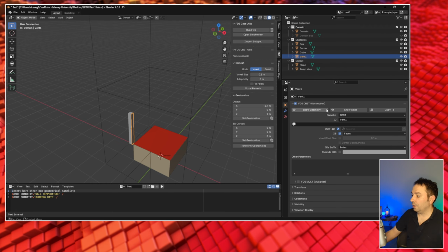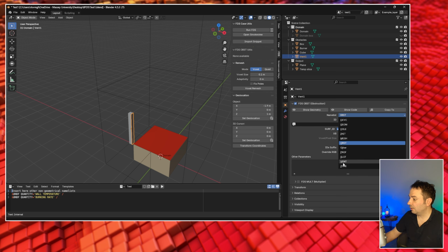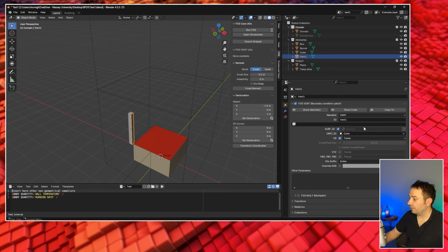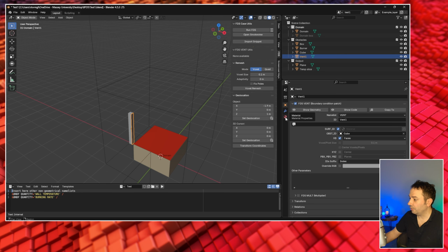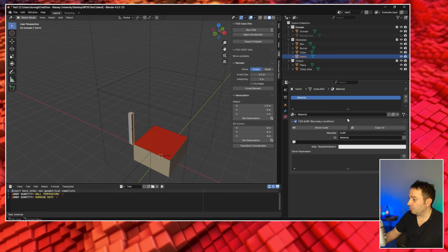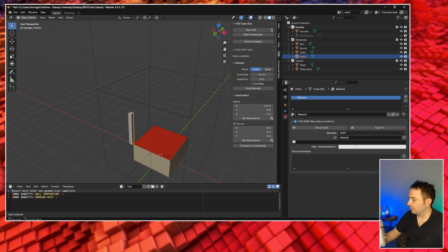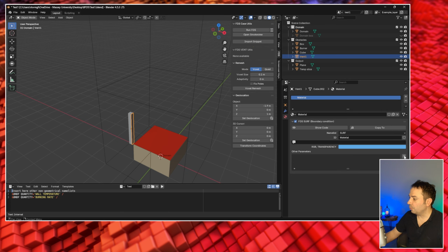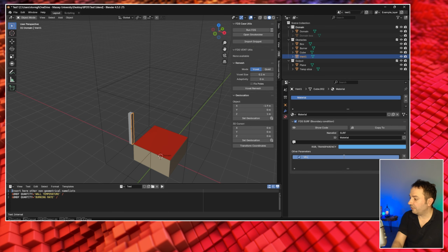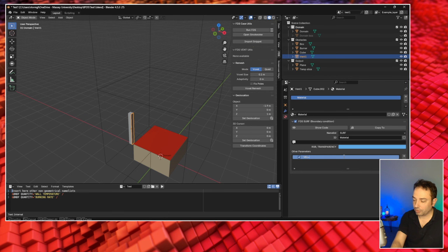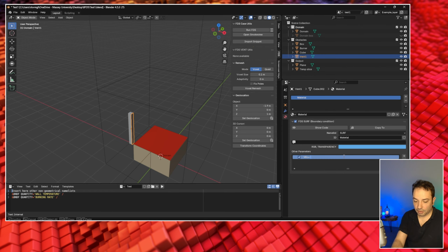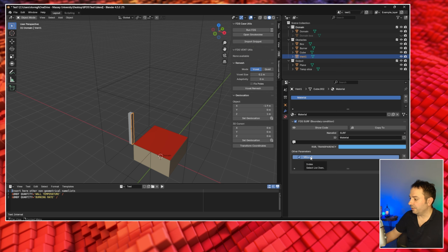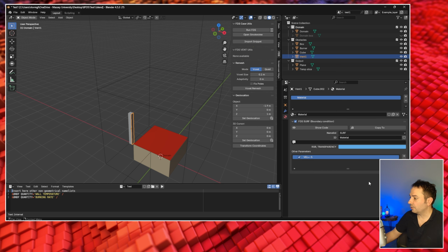So in this case, we need to select vent, and we are gonna define a new material for this vent. And as always, to do it, we need to go to materials, create a new material. In this case, we can leave it. If you want, you can change the color of the material, but we are gonna add a new parameter here to specify that we want flow coming. So we are gonna put w equal -5. So you can change the intensity here depending on what you are trying to achieve.